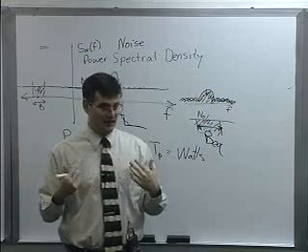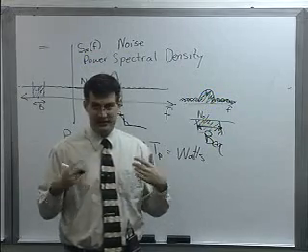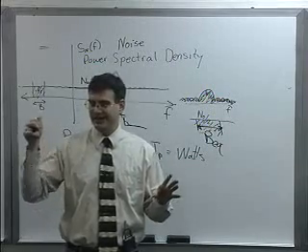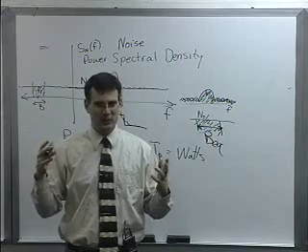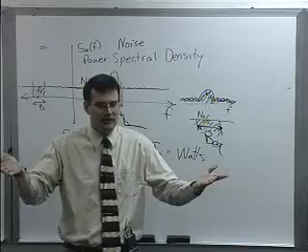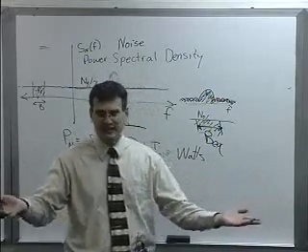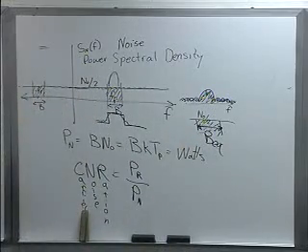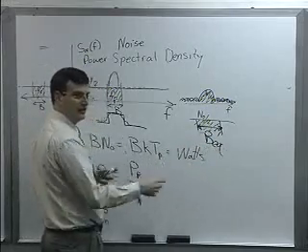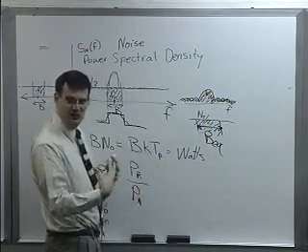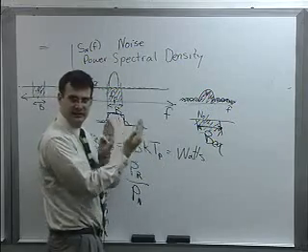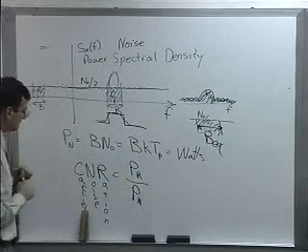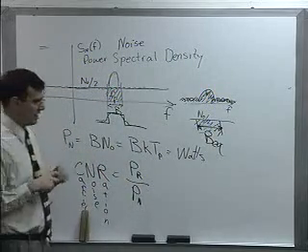In our class, whenever I ask you a question, or if I say something, unless I say otherwise, we're always going to assume that we have these perfect filters and that your noise equivalent bandwidth is effectively the bandwidth of your signal. If it's a well-designed system, it's never that far off. That's just a side note, because you'll see this in the literature. If you ever see that, they're really talking about all the stuff that we're talking about. They're just trying to adjust the bandwidth just a little bit to account for some of these non-idealities. So that's point number one I wanted to make.